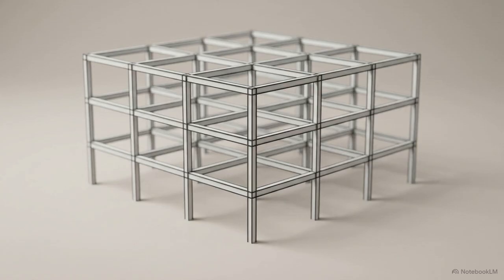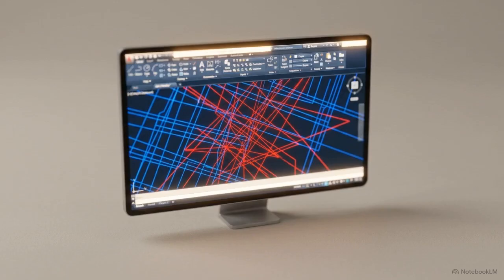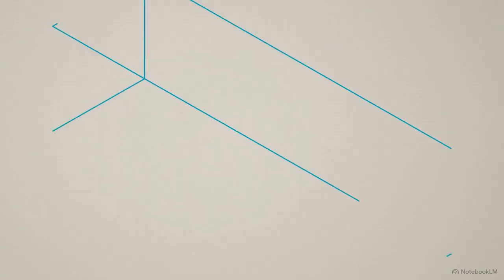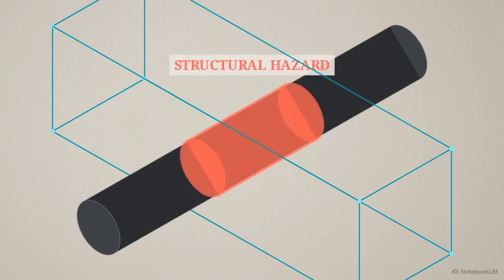While structural drawings build the skeleton, architectural working drawings dictate the enclosure. They specify exact masonry block thicknesses, lintel heights, and floor tile starting patterns to minimize material wastage. Generating these instructions also serves as a line of defense against human error. Draftsmen use this phase for proactive clash detection. This 3D diagram highlights a hazard, a mechanical layout intersecting the load-bearing framework.